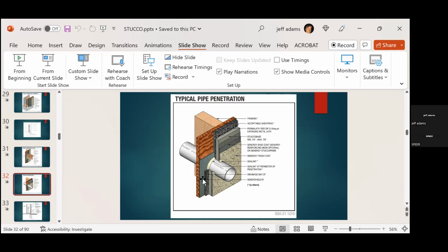Right now, because of things that have been happening since COVID, all of the stucco houses, masonry veneer, and fiber cement siding houses, they're all going to fail. We're going to end up with huge failure amounts because they are putting on the stucco, putting on the fiber cement. They're punching their holes through their WRB and they're caulking it here. Then they're going on the backside and only using polyseal. The moisture gets in because they can't seal it to the WRB. They can't flash it to the WRB like that. It's getting to your OSBs and everything, and it just starts pushing all of this out because it's warping and getting rotted and deteriorated. There's just tons of houses.